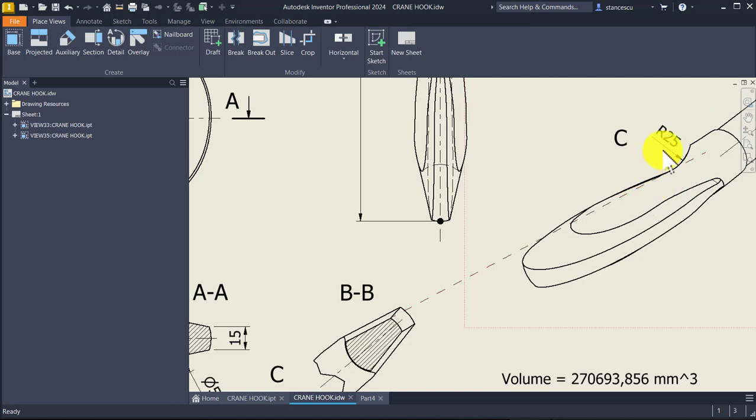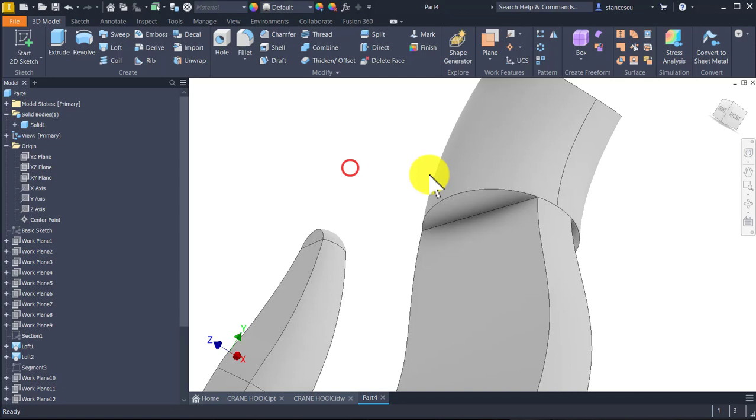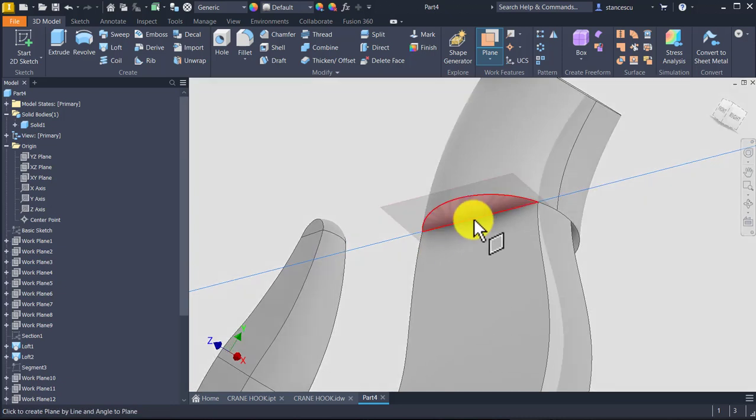In other words, perpendicular to this yellow plane is this axis, so we create an axis, my friends. Axis here and a point in the middle, this point. Now we can create a plane perpendicular to this axis, which contains this point.